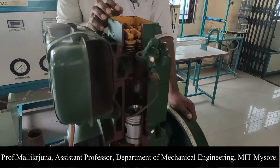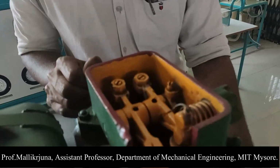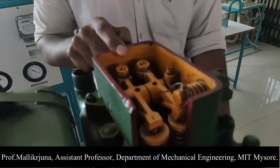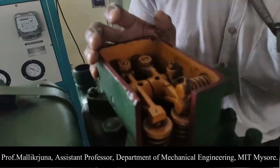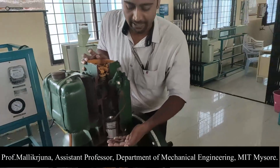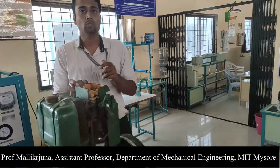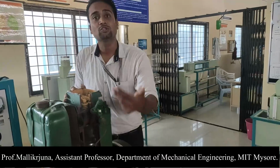Okay, so now at this crank angle, if you clearly observe, the movement of the inlet valve has stopped. So this is the one point that I was looking for: at what crank angle does the movement of the inlet valve stop? That is the question. If you look at the piston's position, the piston moved from TDC to BDC, and again from BDC to TDC it has lifted a little bit, in the sense the inlet valve has been closed after the piston reaches the BDC.